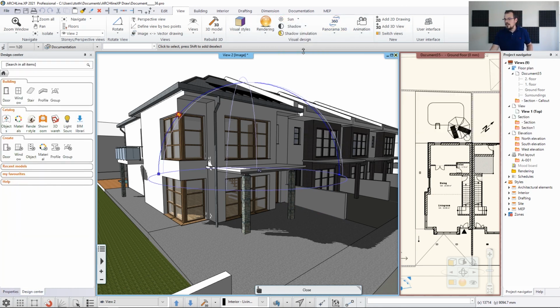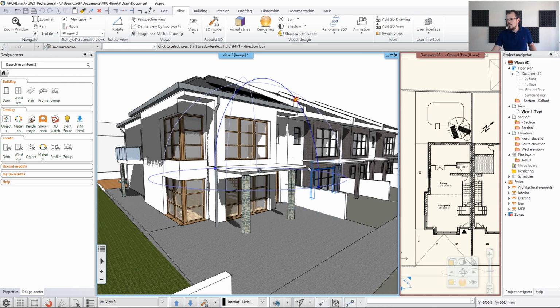And if you do that, you have two main controls you can use. One is where the sun rises and sets, so you can just click on this node and move it somewhere else. Let's move it like so. So now the sun is going to face the building. The other control is how high the sun is in the sky. So let's say the sun is like so. It gives you the right result, but again, it might not be accurate.